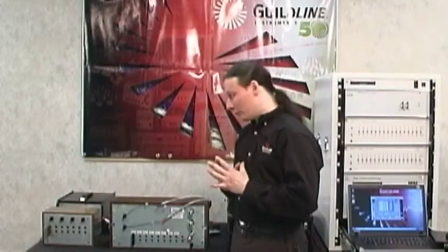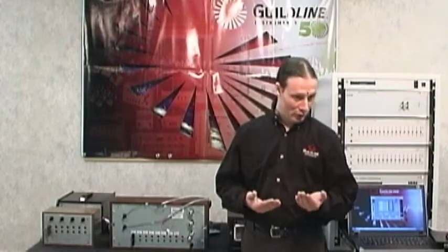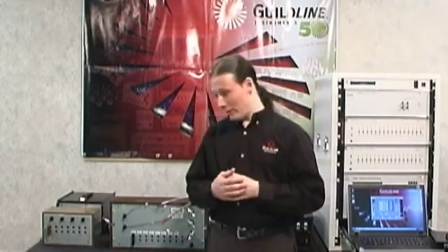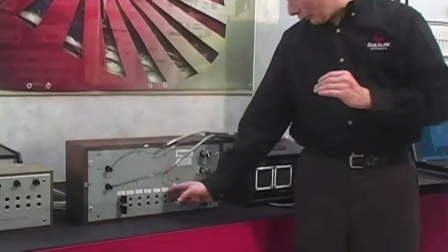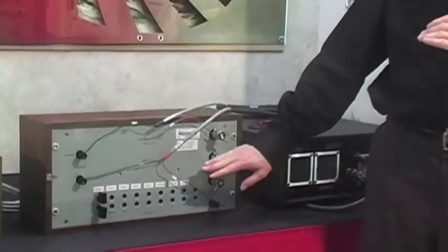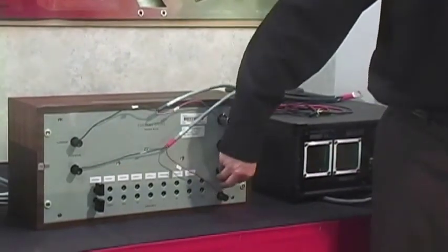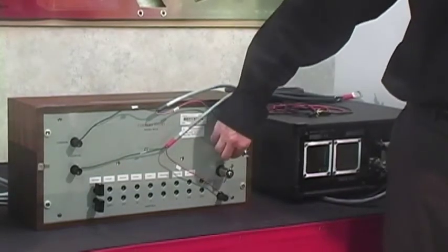And also when you reach a point where you have to connect the range extender, the software will let you know that you're in a range now where you need to use more current, and it'll tell you to use the times 20 range, or times 200, or times 2000 range based on the amount of current that needs to be generated. Also bear in mind that once you get past using lower currents and you get into above 10 amps, you see here we have a 100 amp connector and a 300 amp connector. You want to bear in mind that once you're actually making the measurement for the 100 amp, it has its own independent connection, so you'll have to use that. And when you do your 300 amp connector, you have to use this connector up here.